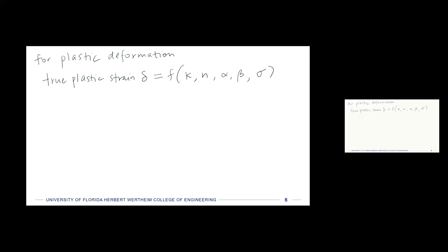And in our case, we don't have just principal stress, we actually have the input pressure and the geometry, so we can relate that easily. We are going to say that the relationships between stresses and pressure still hold. So that would be like our sigma 1 equals whatever P R divided by T, and our sigma 2 is equal to half that. Okay.